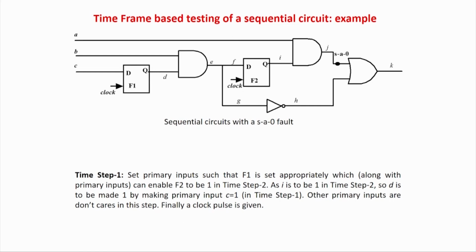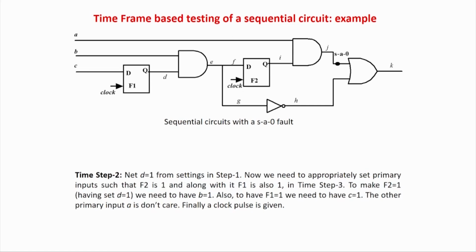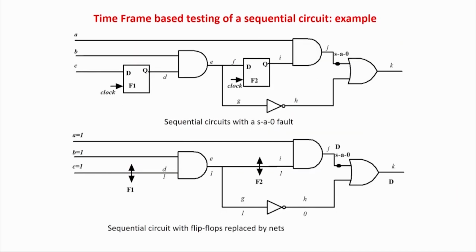That means if you take a path to the primary inputs, there will be 9999 flip flops in the path. So if you make a scan chain, the scan chain length also will be of the level of 10,000, and you will also require 10,000 clock pulses to feed it. So scan chain basically does not save your test application time. It only helps to generate test patterns quite faster, because you need not do all kinds of backtracking about what values will be required to put this value at 1 and at this gate, because the flip flop will be directly controllable.